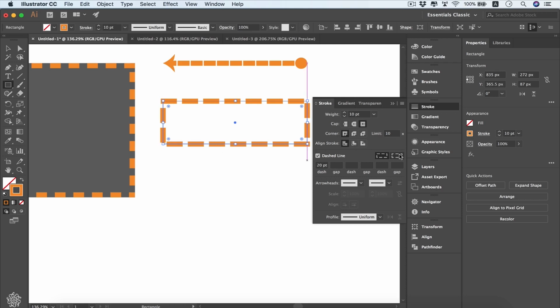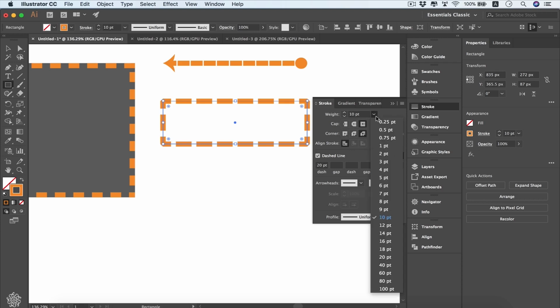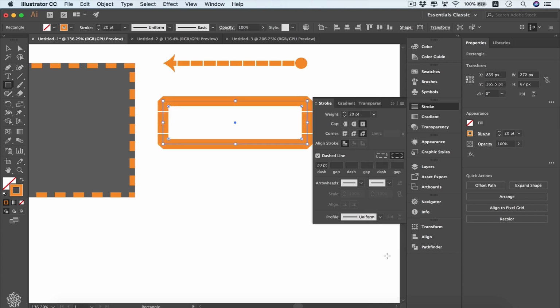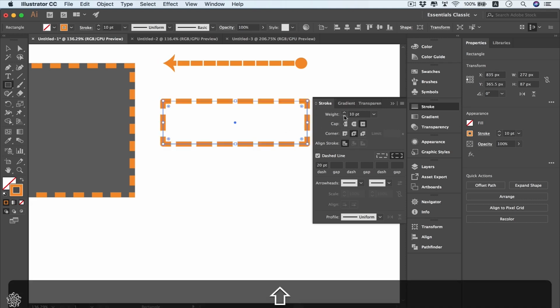And if we choose that option, you will be having more organized corners. However, if you choose that one, it will be going randomly without being calculated in here. So I usually prefer that one to use it. And here we can be choosing round corners like that, or even bevel corners. If we increase that one to 20 maybe, you will be seeing these bevel corners and these are round corners. However, I'm gonna set it back to 10.